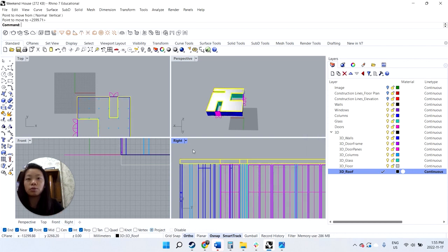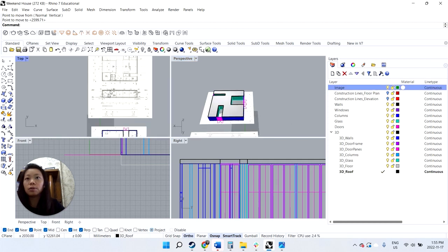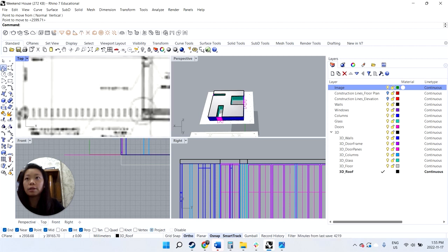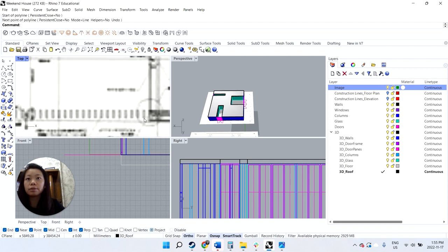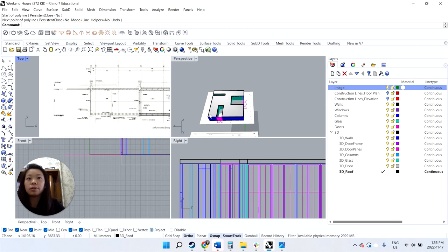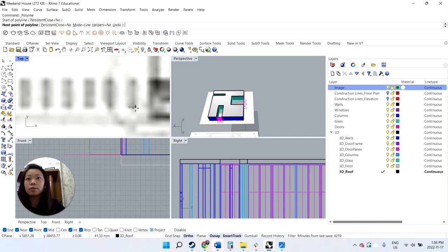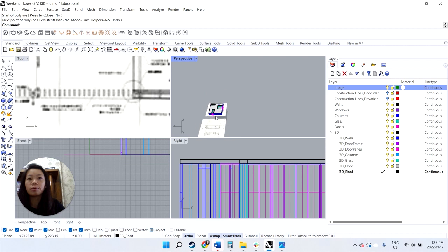I'm going to move it, I think, extrude it down, but there you can see it. And then if you look at our sections, it would show in this one. It's kind of like, let's say, they're separated by every 100, right? So if you do slats along the way, there's like a 100mm gap in between them, and let's say they're 50 by 200. So again, we can kind of model that in the roof.